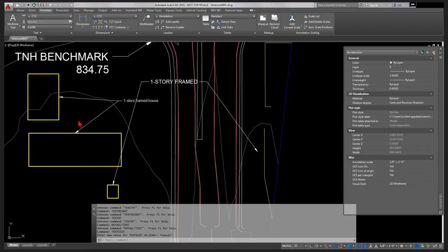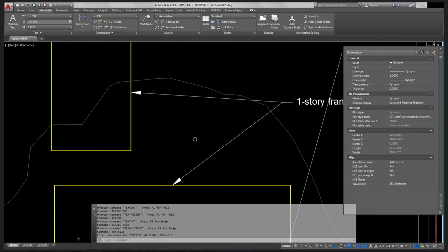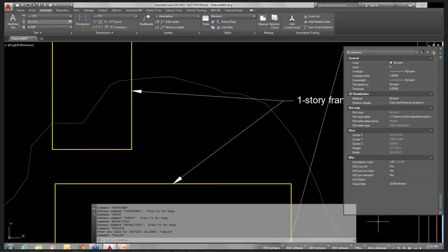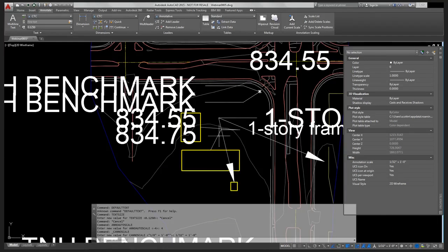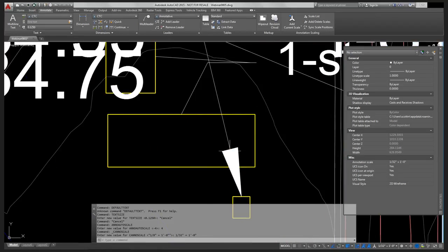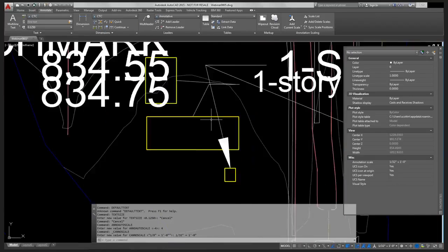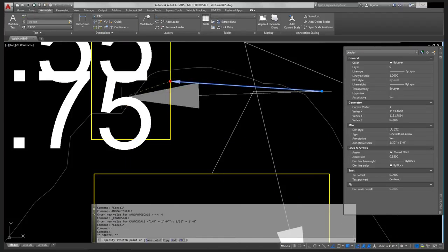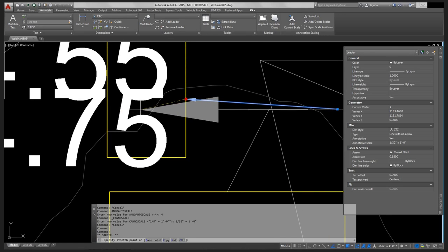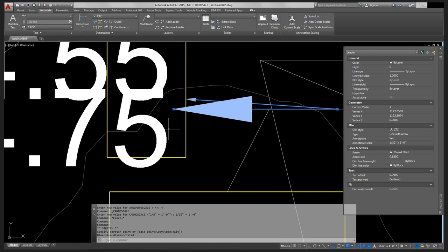I forgot to unmute myself. Almost started to talk without having a microphone. So yeah, just to see the arrowheads change. Let me add text height in here. So now if I switch my scaling, I'll jump this up to 330 seconds. And now you can see that this arrowhead is quite large. And the arrowhead on this one is actually so big that it won't even display until right about there.